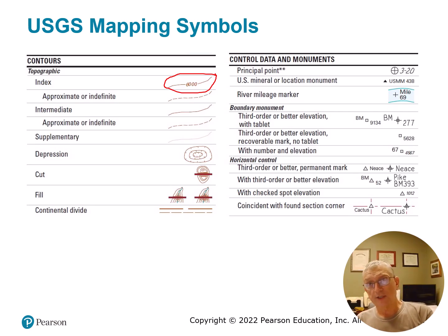And typically what we actually do, these are for quad maps, because dashed lines imply uncertainty. But when we're preparing topographic maps where uncertainty is not an issue because we have good data, we'll typically do dashed lines just because solid lines tend to overpower or overstimulate the drawing. And there are other solid lines on the map that they conflict with, such as property lines or setback lines or buildings. And here's a depression. You remember we got the tick marks that point to the low spot.